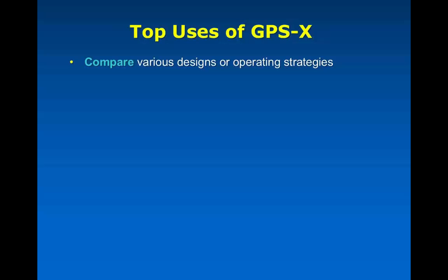However, I would say probably even more common than that is using models to verify existing plant capacity. This is particularly used where somebody is modeling a wastewater treatment plant for the first time. A plant has been running, it may be running quite well now, it may have lots of capacity now, but the people operating that plant want to know how much capacity they have left, and a model is an excellent way to figure that out.